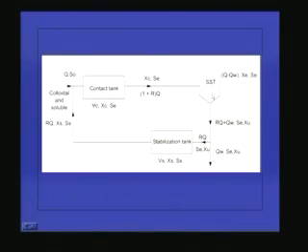Here the biomass gets settled, along with the colloidal particles, but we are giving sufficient time here also, 1.5 to 2 hours in the secondary sedimentation tank. Meanwhile the microorganisms will secrete extracellular enzymes which can hydrolyze the colloidal particles. So along with the biomass, the colloidal particles also come to the stabilization tank.